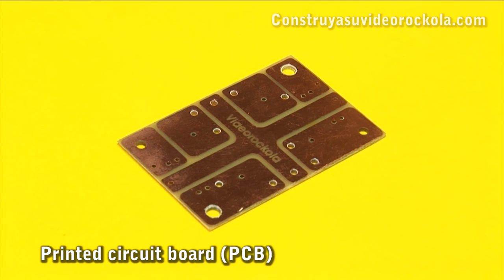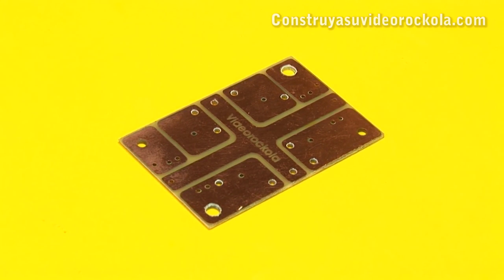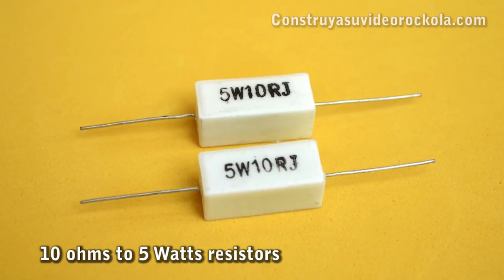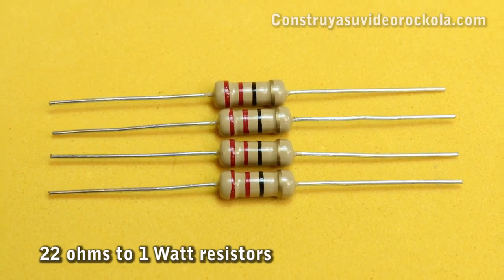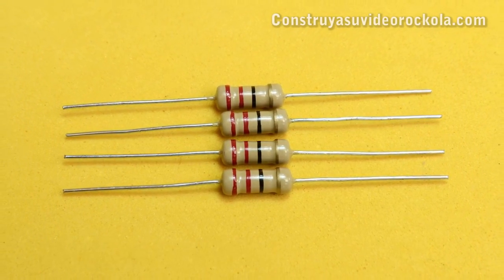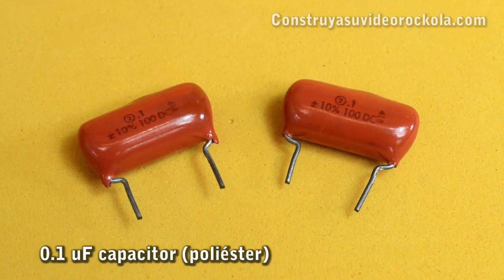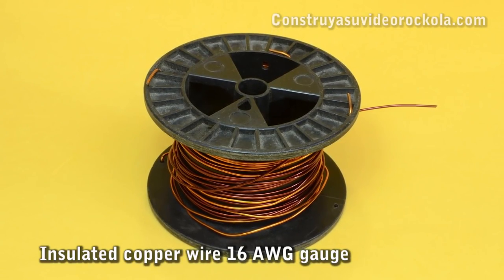Materials. Printed circuit board, you can make it in fiberglass or bakelite. In the video description, you can download the PDF file. 2 resistors, of 10 ohms, at 5 watts. 4 resistors, of 22 ohms, at 1 watt. 2 capacitors of 0.1 microfarad, at 250 volts. An insulated copper wire, 16 AWG gauge.